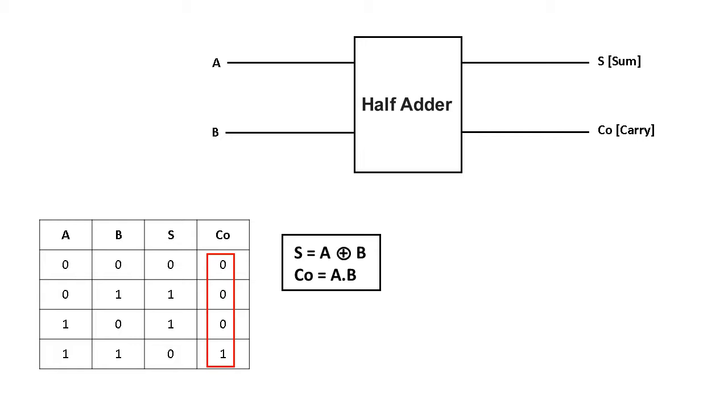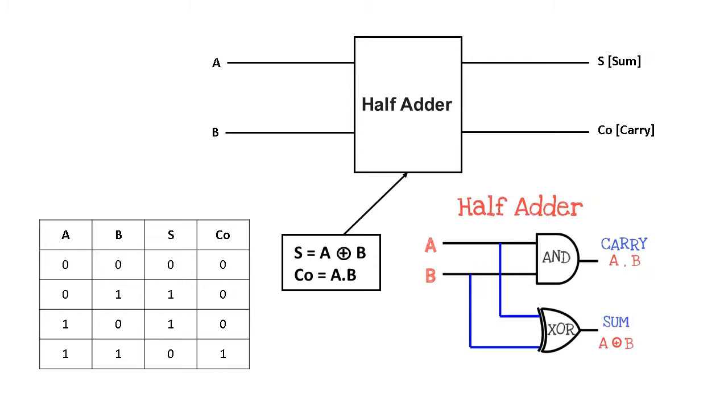So that means we work with the AND gate, A into B means AND gate. So this is how we can represent it. Let us now draw the circuit. You can observe this particular logic of sum and carry is implemented through this half adder, and this is the circuit diagram. If you closely observe the half adder circuit diagram, A and B both are provided as the input.